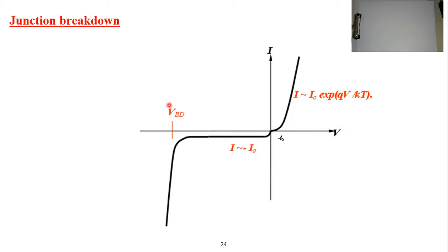Now, our target, or maybe our challenge in this part, is to transform this IV curve into a circuit element model, to insert this diode into a circuit and start analyzing the circuit containing this diode. So we are going to make some simplification to this IV curve so that we can insert it in our circuit model.